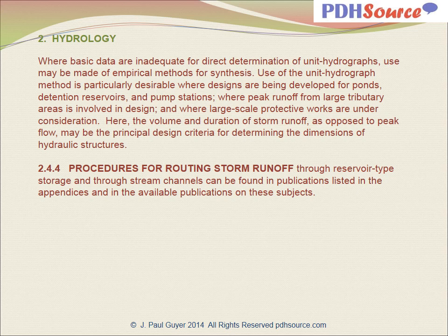Here, the volume and duration of storm runoff, as opposed to peak flow, may be the principal design criteria for determining the dimensions of hydraulic structures. The procedures for routing storm runoff through reservoir-type storage and through stream channels can be found in some of the publications listed in the appendices.